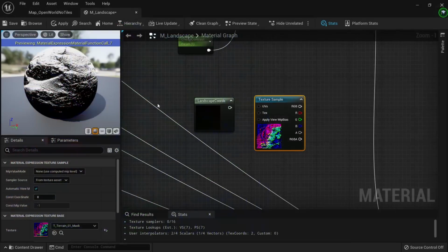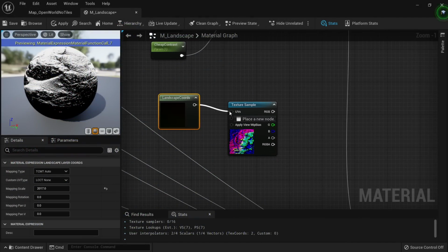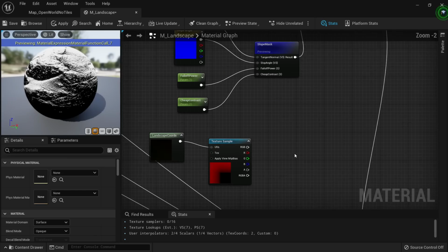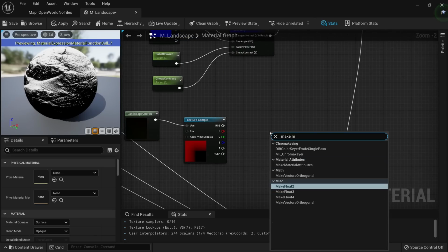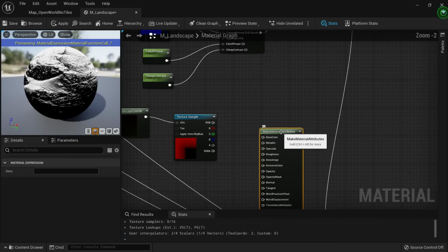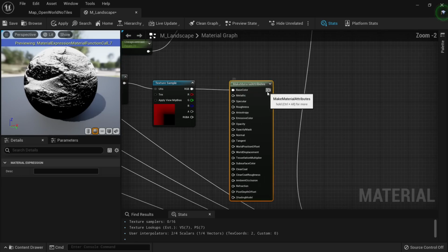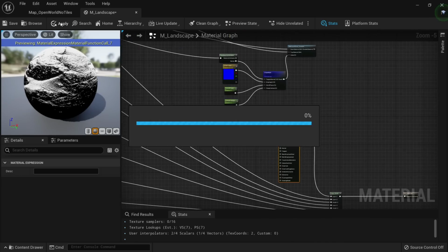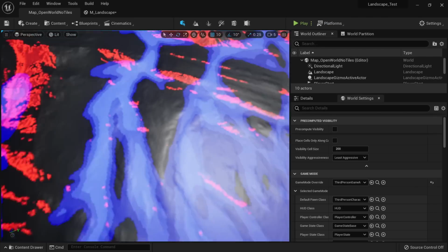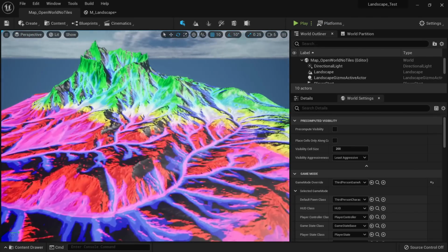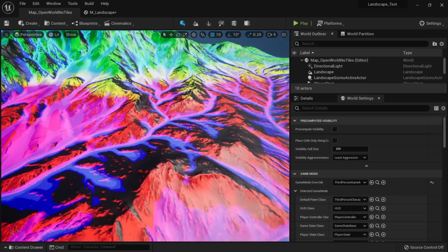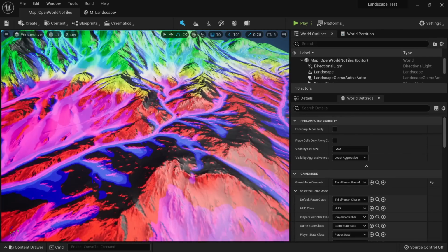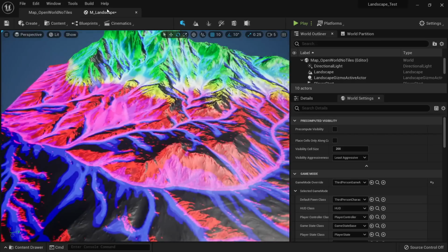Okay, and now that I do that, I just click here, and let's preview this to check how this works. So we're going to make material attributes, so we can take a look at how it will look. Put the base color here, and then put this into the layer 1. Click apply, and there you go. Now you have a mask here that is using all your landscape. Now that's great. So let's try to make something out of this.